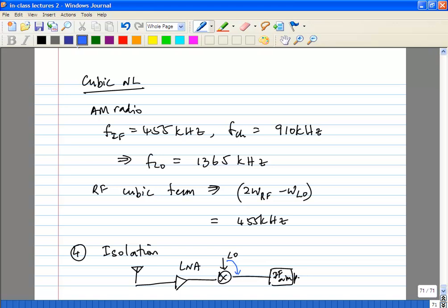Your RF signal is in microvolts. After the LNA, it will probably be in hundreds of microvolts, maybe millivolts. Your LO signal is usually in hundreds of millivolts, or maybe greater than a volt. So there is every chance that the LO signal coming in is much larger than your RF signal. What happens? You could saturate your IF amplifier. That is your LO to IF feed through.